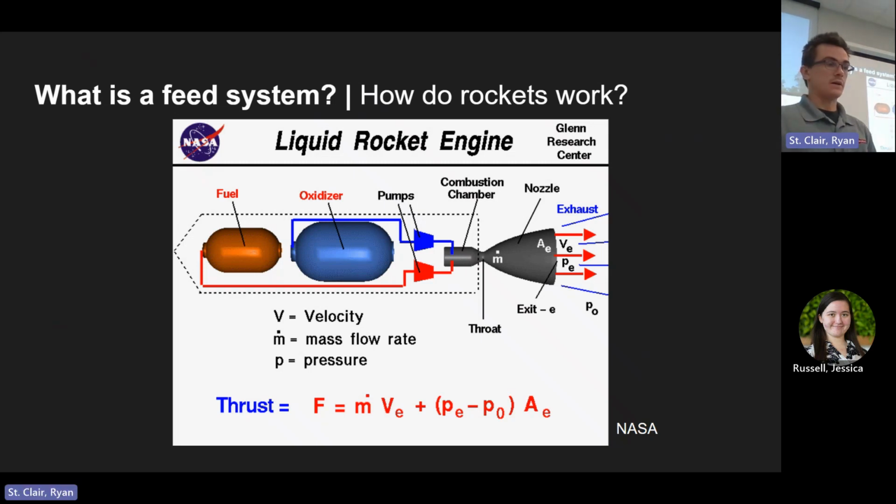In order to do that, fluids flow from high pressure to low pressure. So you have to ponder, how do you get those propellants up to a higher pressure than the combustion chamber pressure? There are a couple of ways that people do that. If you look at any industry rocket, it'll tend to use turbopump systems. Basically you burn a little bit of propellant in what's called a preburner, and that drives turbines that spin pumps, and those pumps provide the pressure to get the propellant from the tank to the combustion chamber. Turbo machinery is a very complicated project, and you never see that happen on student teams.